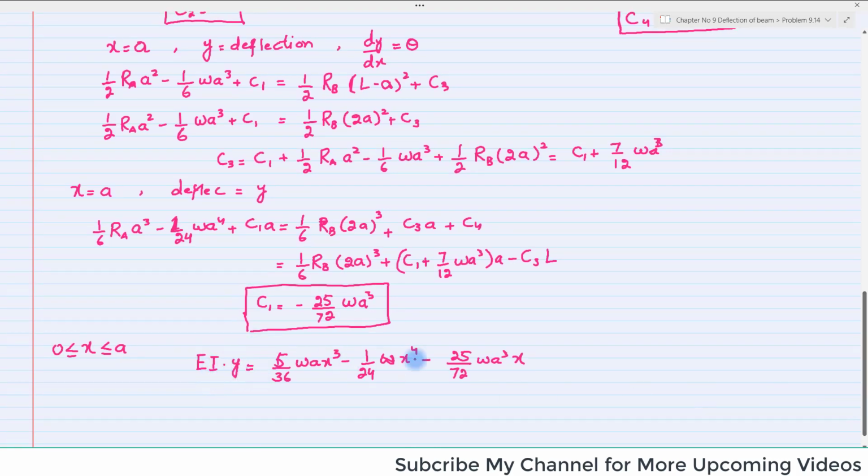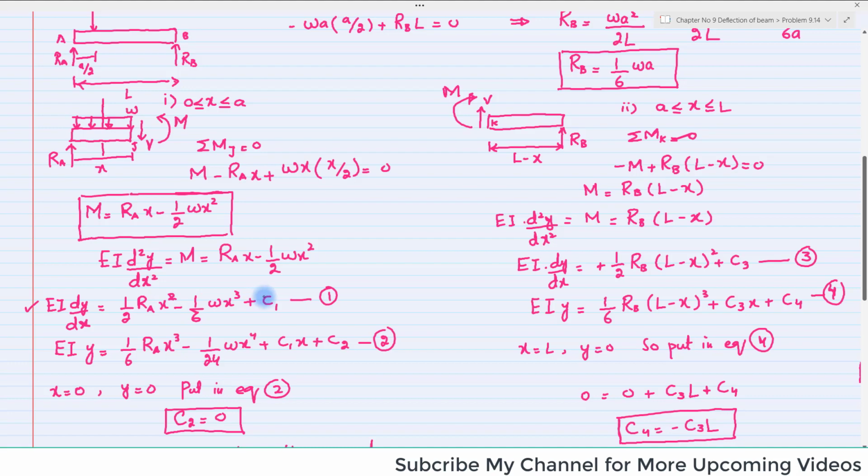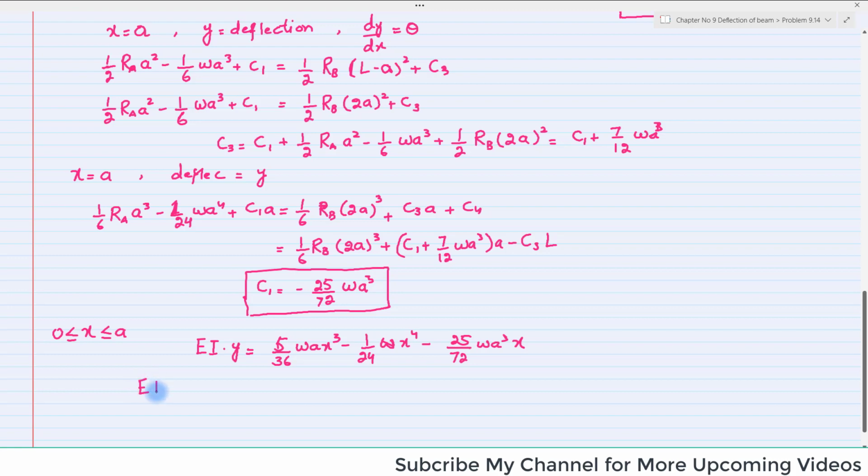Clear? And again, you can also put the value of C1 in the equation and R A in equation 1. You will get this equation: EI dy by dx equals 5 over 12 W A x squared minus 1 over 6 W x cubed minus 25 over 72 W A cubed. Or you can take the derivative of the previous equation to get this.